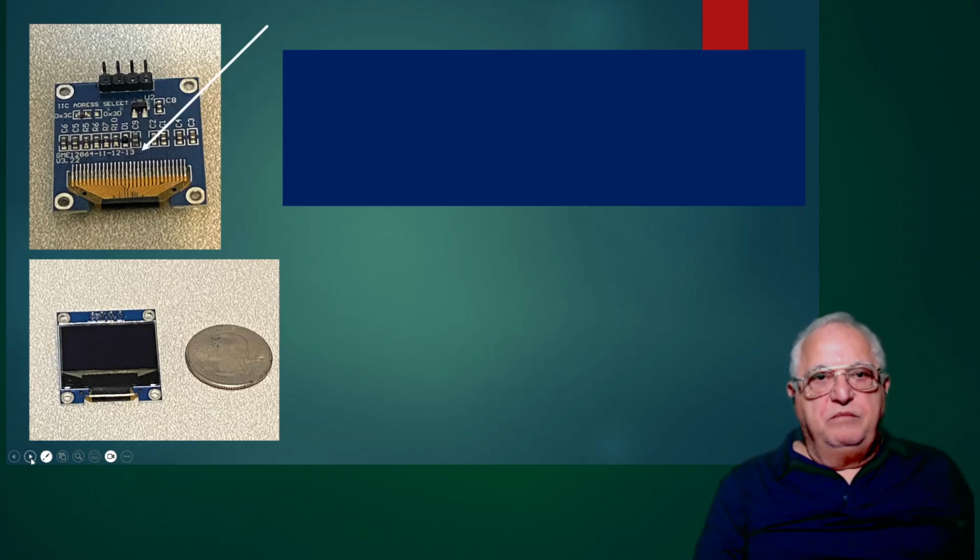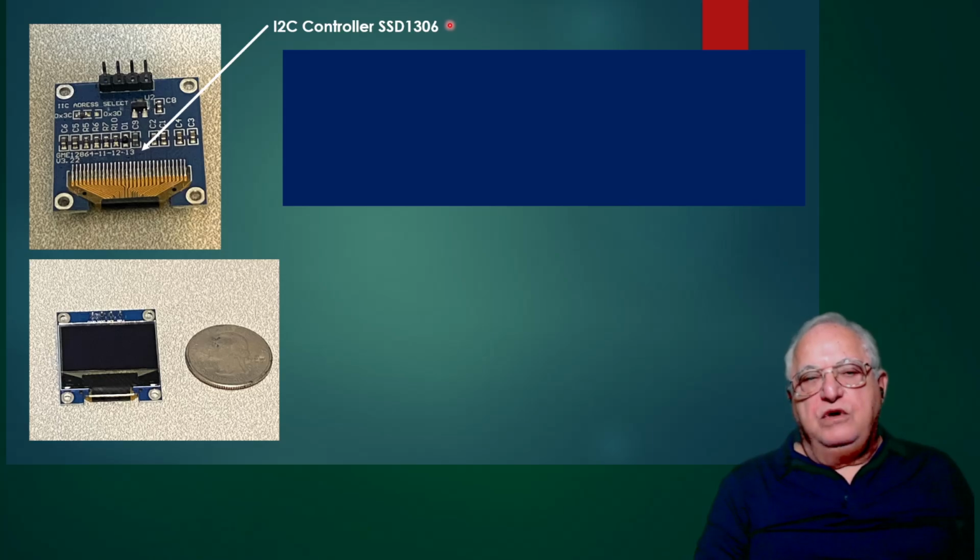Now that's the part number. We looked at the part number and found out that the controller associated with this display is the SSD1306. That's important information because that's how we go about finding the data sheet associated with this display. So let's look at some of the detail.